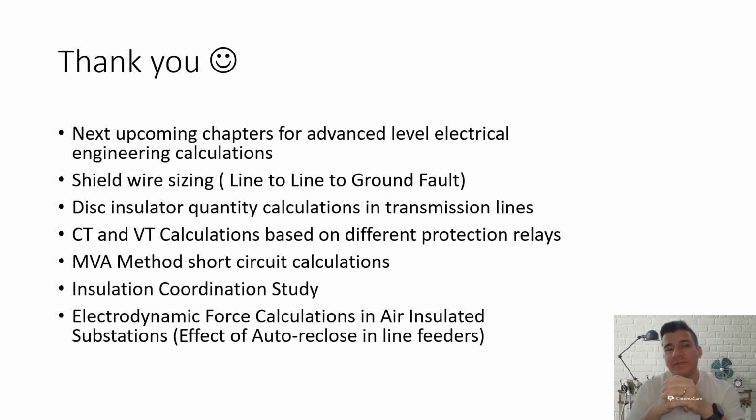And there is one different chapter which I really like: electrodynamic force calculations in air insulated substations. By the way, this is, according to me, one of the main chapters of being a power engineer. And you will see so many things there. Effect of auto reclose. How will we select a proper size of post insulator and tubular bus bar?